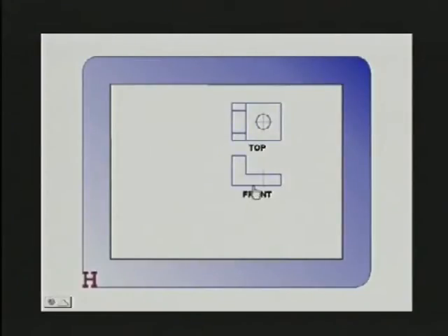But for the purposes of today's discussion, we're going to concentrate on third angle projection, where we start with the front view, and directly above that, we place the top view. Directly to the right, we position the right side view. Now, this alignment is very important. Notice that the height is measured in both the front and the right side view, and they're directly aligned. The top view holds the width, and the front view shows the width, and they're directly aligned. These are the 3 views you're used to seeing so far, but there are 3 more.